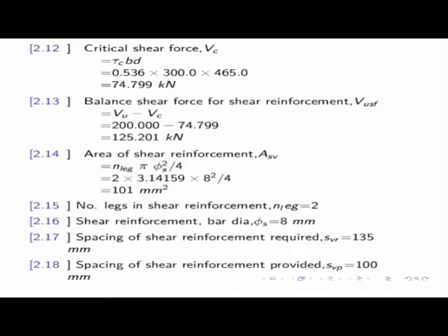Now the balance shear force we are having is 125.201. That means for this I have to provide the stirrup, because for this additional shear force, we have to provide stirrup or shear reinforcement.